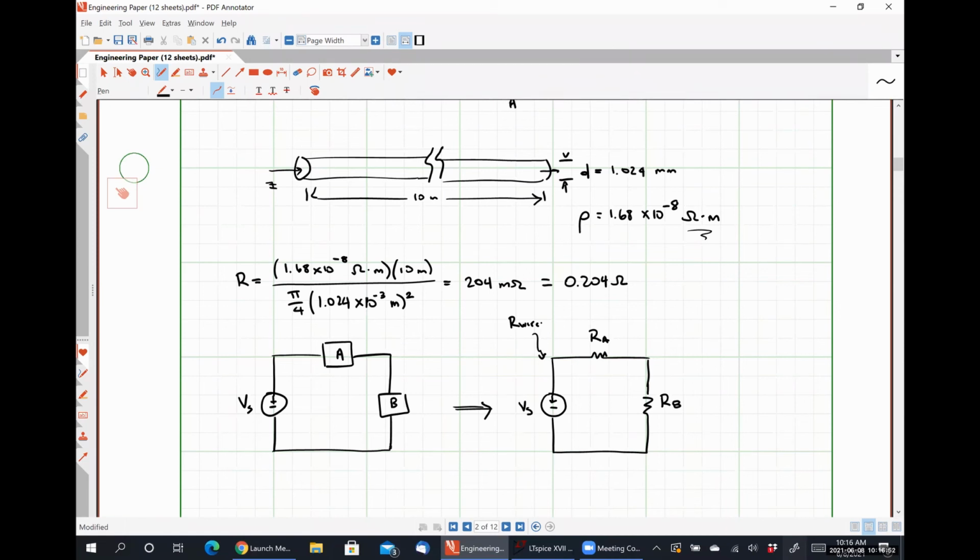In the overwhelming majority of circuits that we're going to deal with in this class, we are going to treat wires as having 0 resistance. But there are some applications, particularly in high power applications, like setting up systems to feed motors and HVAC units and stuff like that, where the resistance of the wire is actually important enough to merit determining it and including that in our calculations.